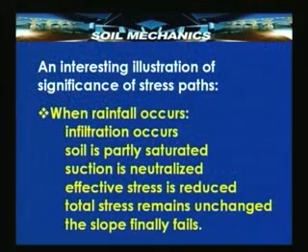And you know what will happen if the effective stress goes on getting reduced: the shear resistance goes on decreasing, and therefore ultimately a stage is reached where the effective stress reduces to such an extent that the slope finally fails. But during all this process, we must remember that the total stress in the system remains unchanged. Neither an external stress is applied nor an internal stress is disturbed, just the pore pressure goes on changing with total pressure remaining the same. This is a very interesting concept that has been developed by Brand to explain the phenomenon of rainfall induced landslides.